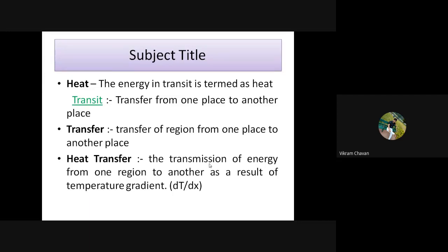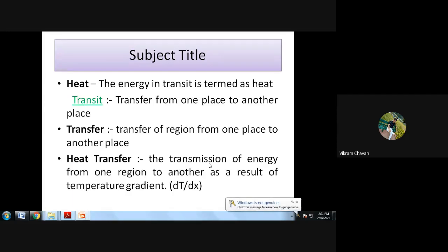And that we have studied in the first law of thermodynamics. But the second law deals with the heat pump, and it is about refrigeration also. If you want to transfer heat from a low temperature region to a high temperature region, then you have to do some work on that particular device, and that is a heat pump. The second law of thermodynamics says that without doing any external work, you can't transfer heat from a low temperature region to a high temperature region.